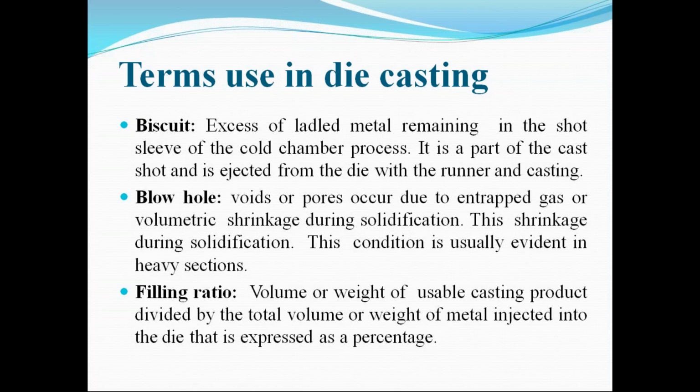That means a huge amount of material is available, so the heat capacity is higher, and it takes a longer time for solidification. So that kind of problem can happen. Due to the entrapment of gas, it cannot escape, and ultimately it makes an impression on the product surface, like voids or pores. This is called the blowhole.